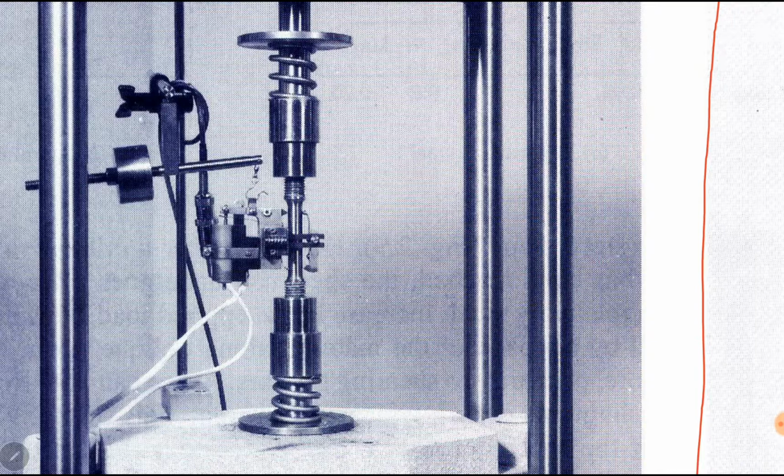Here small d is equal to 0.618 inches and the capital D, this diameter, is 1.07 inches. E is the same for both portions, which is 29 into 10 power 6 psi. Loads are different. At the end, there's 30 kilopounds, then 45, then 75 kilopounds. We have to find the total deformation of the steel rod, delta.